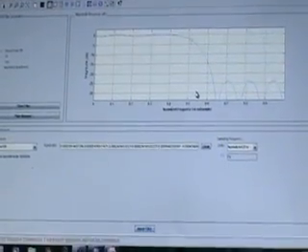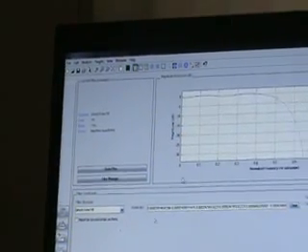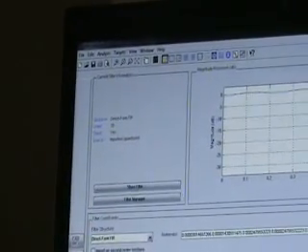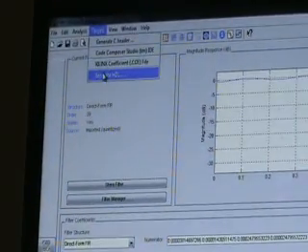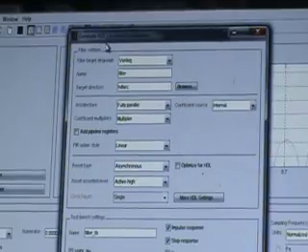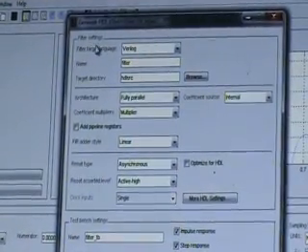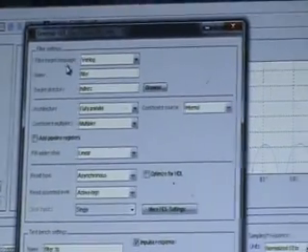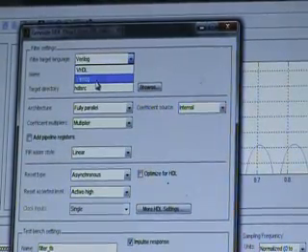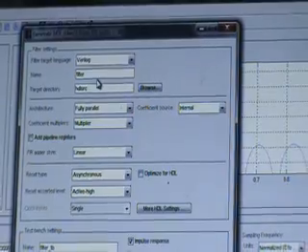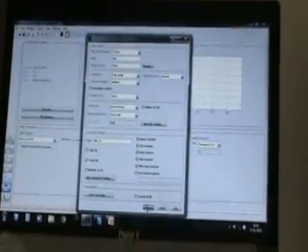Now if we want to find the power, area or delay of the filter which we have generated, then we have an option in FDAtool which is used to generate HDL or VHDL code. In this generate HDL, in filter settings, we have filter target language. We can select it as Verilog or VHDL. In this video, we will see how to generate Verilog. And we click on generate.